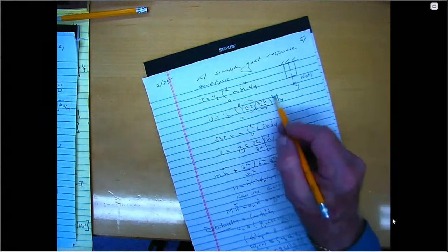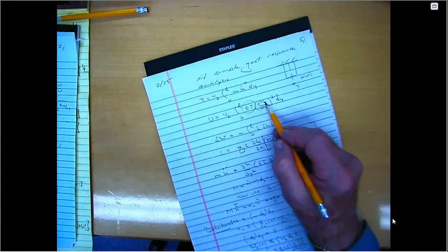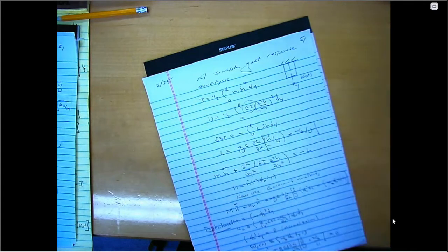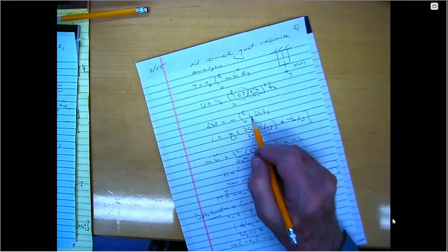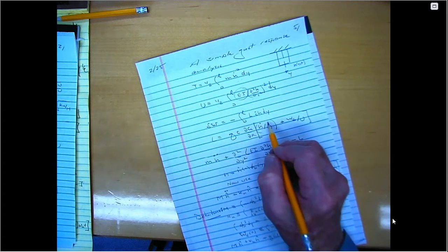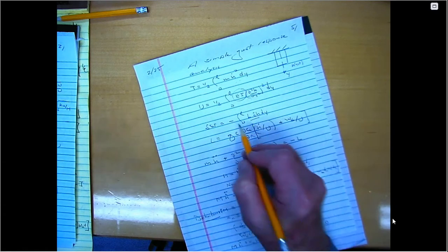But notice it's the same form, a quadratic form. But now it involves a second derivative with respect to y because it's bending of a beam rather than the twisting of a rod. And the virtual work is now no longer the moment times delta alpha. Now it's the lift times delta h, because force acting through a distance gives me work. And there's a minus sign